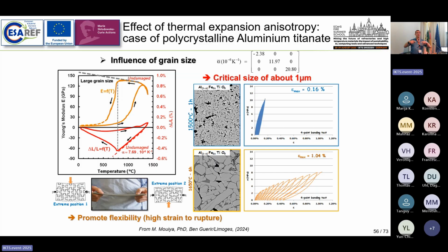And so there are different parameters which make this material a very good candidate for thermal shock. If you look at the intrinsic property of the crystal, okay, with an average thermal expansion of 10, you should forget thermal shock applications. But in fact, no. The thermal expansion on average is quite huge, but due to the microcracks that you can play with in this system, it becomes a very famous material for thermal shock because of the cracks that you can introduce due to that.